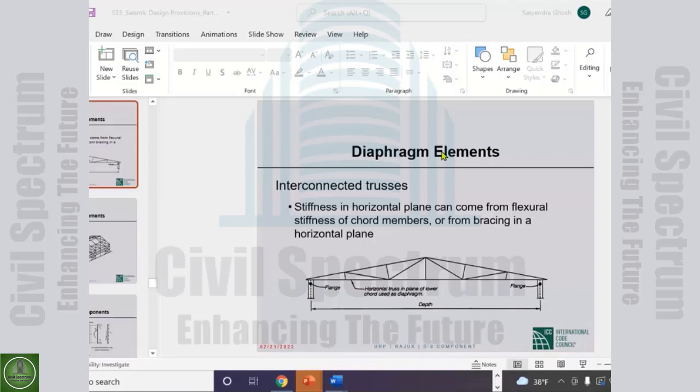So in commercial design software, the shear wall force is used in some load combinations just at the top of the base and requires a lot of rebar. What would be the remedy? Or do you think it is correct?